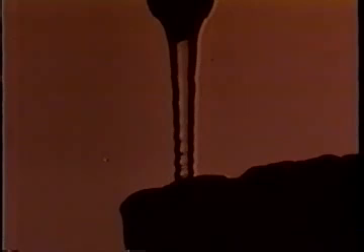Smoke rises because it is lighter than the surrounding air. The smoke plume is steady near its source. Further up, waves occur. The plume becomes unstable, then turbulent. Instability is the first step in the chain of events which generate turbulence. A capillary jet of water from a tap may be stable and smooth or unstable and buckle, depending upon its length.